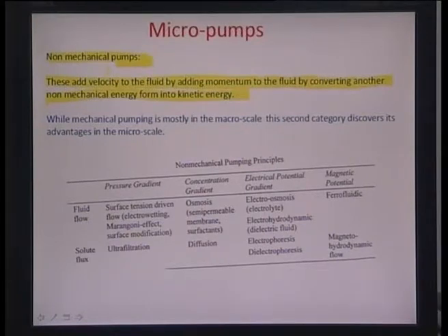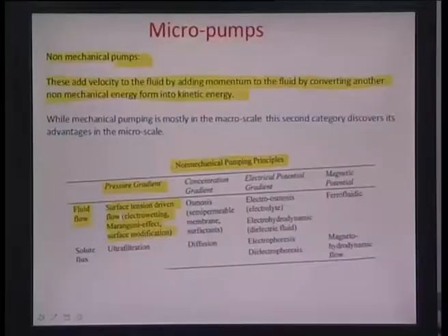There are various principles of non-mechanical pumping. It could be a pressure gradient driven flow, as in surface tension driven flows, electrowetting, the Marangoni effect, which I showed in the case of thermocapillary valves some time back, and also pressure gradients created by surface modification. You can create a hydrophobicity gradient, and that could help in transporting water towards the hydrophilic side from the hydrophobic side. So, that is one of the non-mechanical pumping mechanisms.